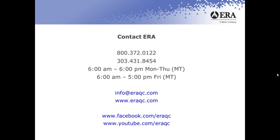The important thing is that you make sure that before you do the testing itself, before you lay out your aliquots, that you make sure that the pH is between the 6.5 and the 7.5 range.